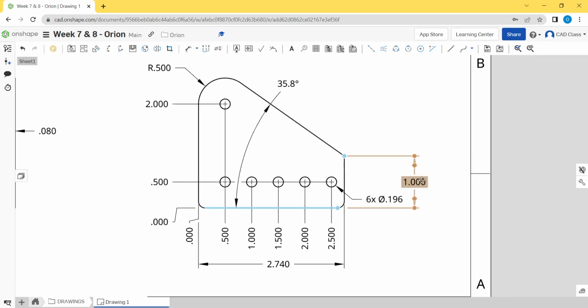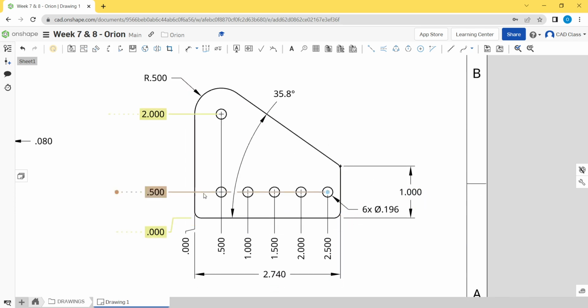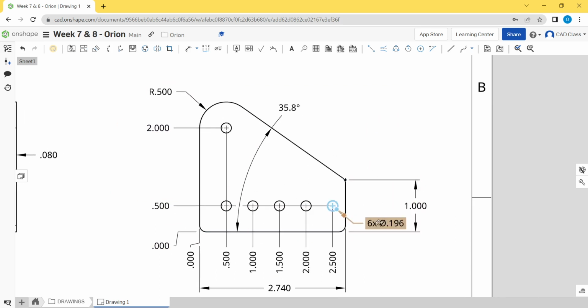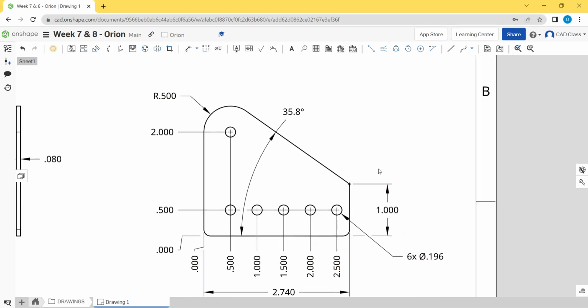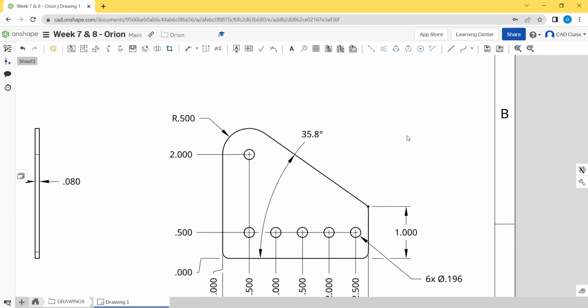All right, so then that tells us that this is 1 inch high, because the way that you would typically make this part, if you weren't doing this in the CNC router, right? If you did this in the CNC router, you just throw the file in and it would just cut the profile and you wouldn't need a drawing at all. But basically, if you were making this on a mill or something manually, you would make all of these corners sharp.